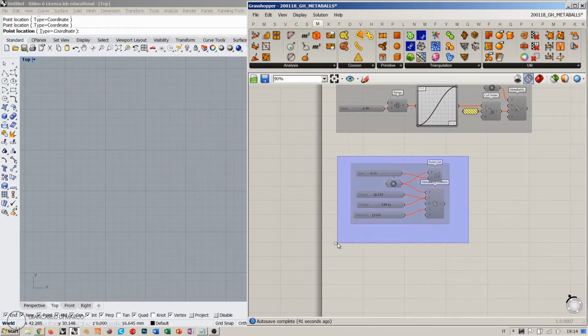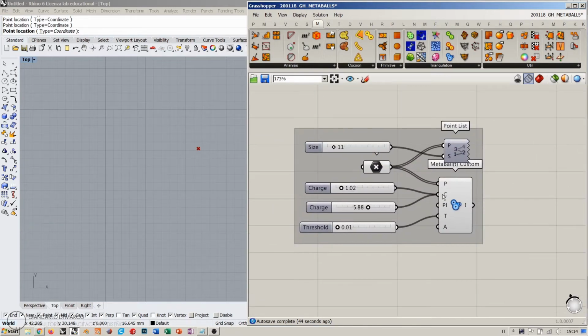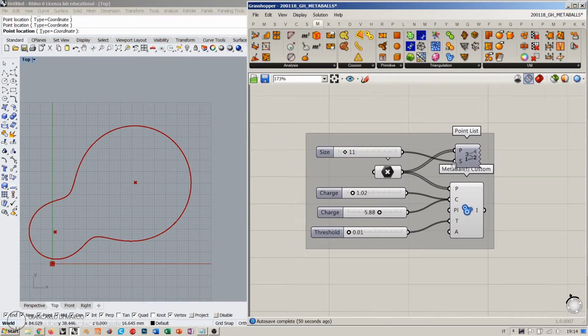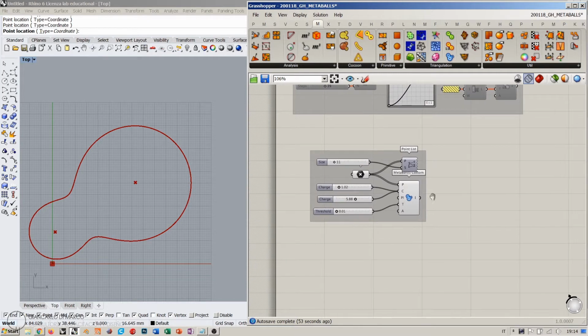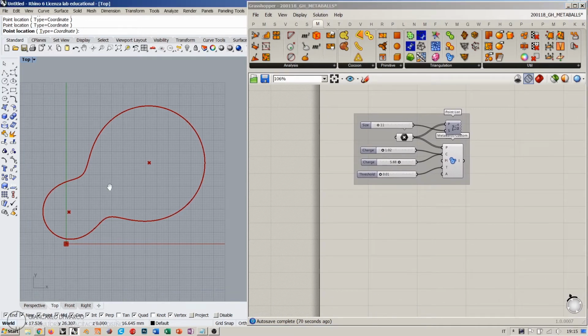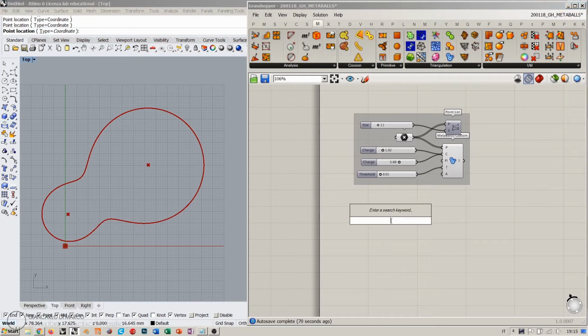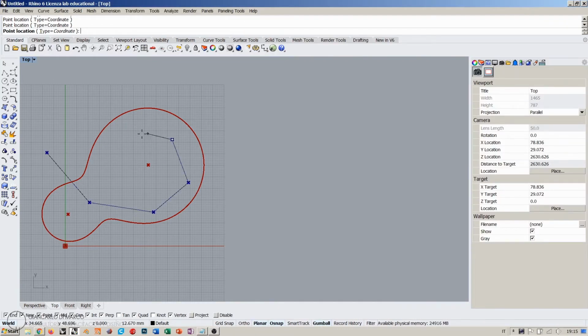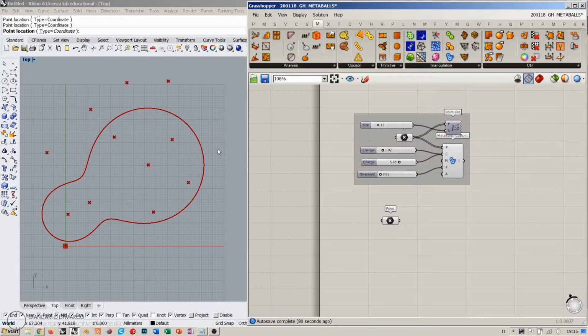And then there is the Metaball T custom, where we can also work with charges. Okay, now in this case it's absolutely interesting because we have at the same time two parameters that affect both the position of the Metaball curve by using the threshold parameter, and also the shape of the Metaball curve, which are basically the charges. Okay, so let's say, for example, that I take a new set of points like this, set multiple points like this, okay, all along a curve.